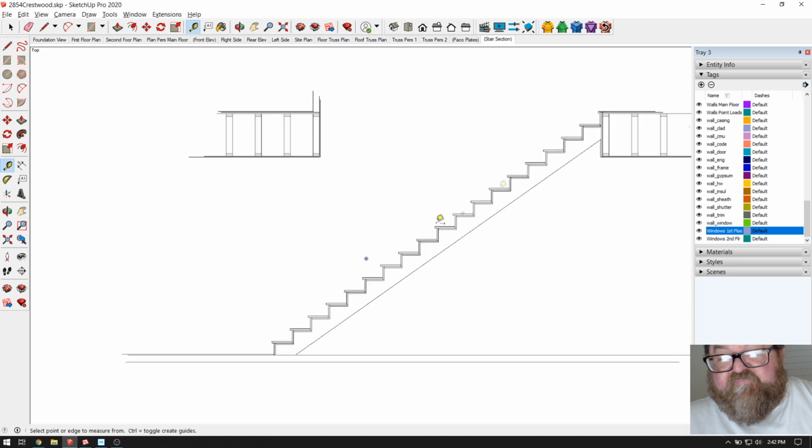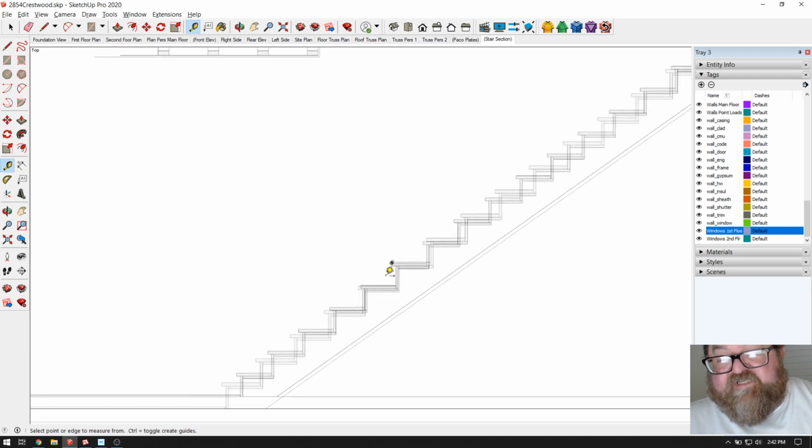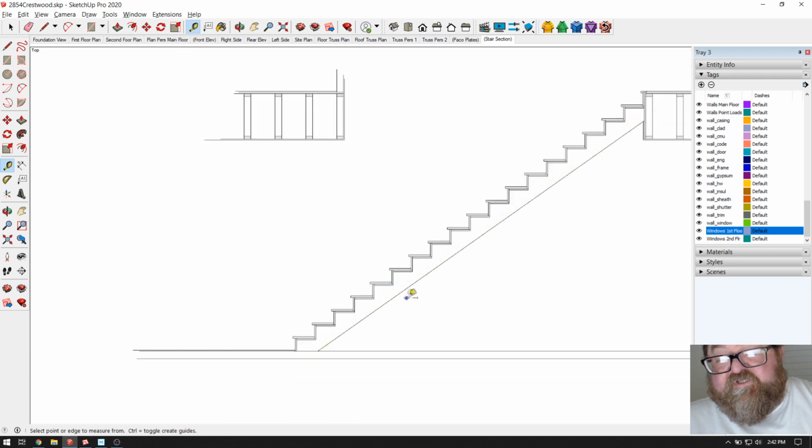But you're struggling to make these risers. I wanted to make these risers 7 3/16. The other option was 7 5/8. You see, a little steeper stair would have pushed this back, and I would have had that extra headroom.